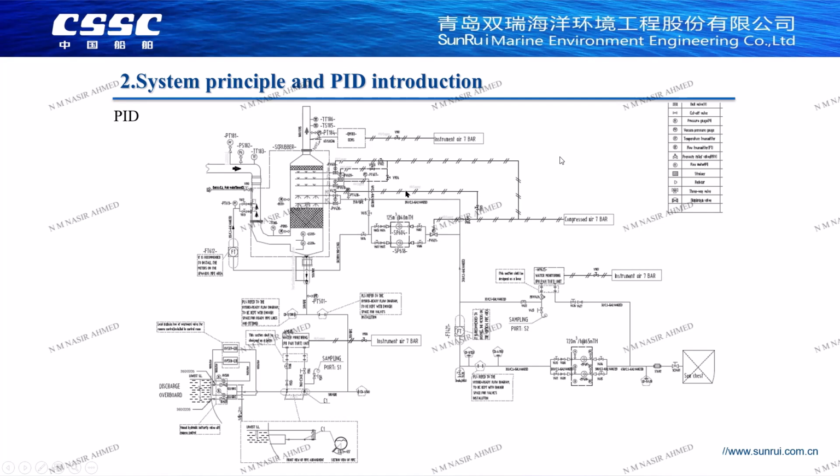To wash the flue gas, we have a water quality analyzer installed at the inlet. The analyzer samples and analyzes the incoming water quality. Looking at the main road, one route goes through 2 pre-spray pumps. What this pre-spray pump does: water is sprayed to the secondary tower of the desulfurization tower.